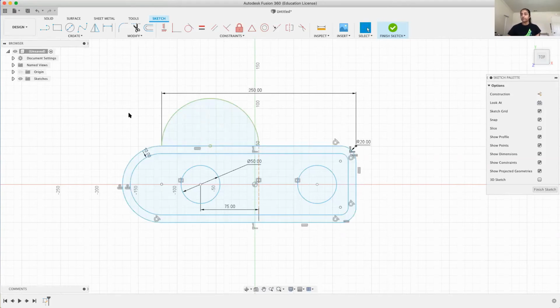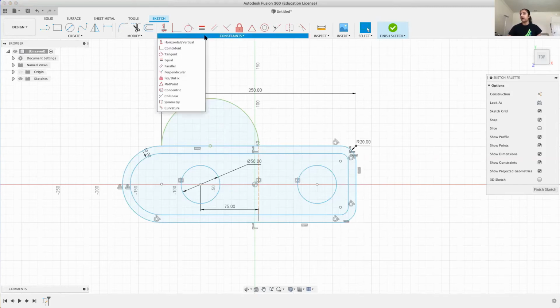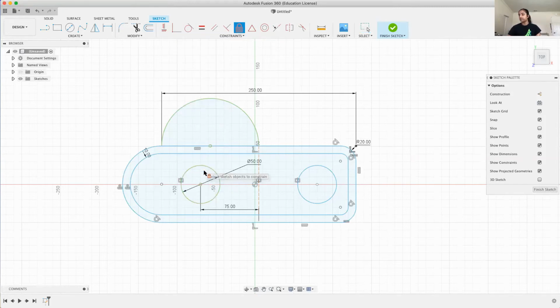Now, there's one other thing that I could do, which is if I fix an object and there are essentially so many relative positions based off that object that affect another object, the other object becomes fixed as a result. That might not be happening right now, but there are times that objects will become fixed like that, and it will cause it to be outlined in this kind of black color, like it is when I'm highlighting it. And so essentially your goal when you're sketching something and you're dimensioning and putting all these constraints in is to make everything have this kind of black outline border.